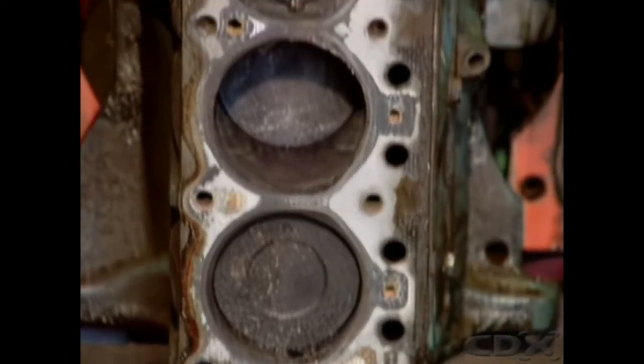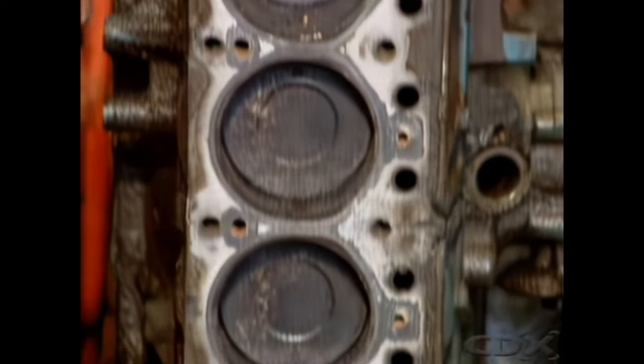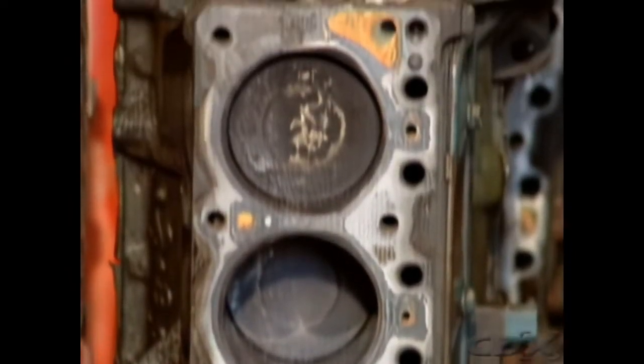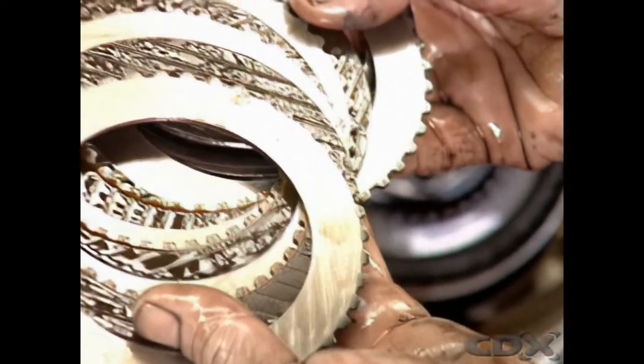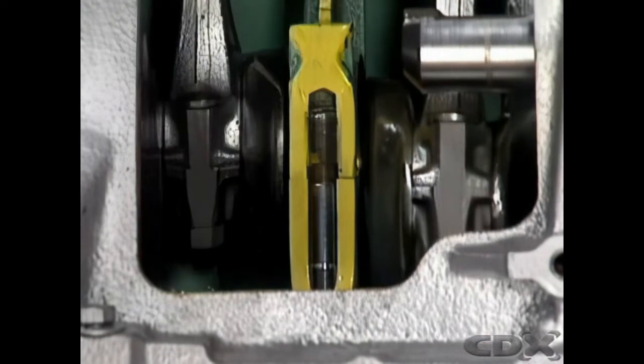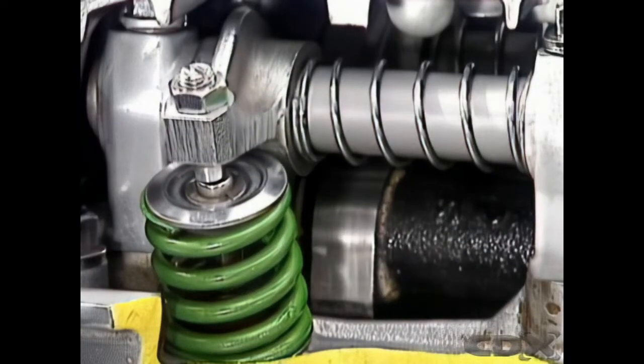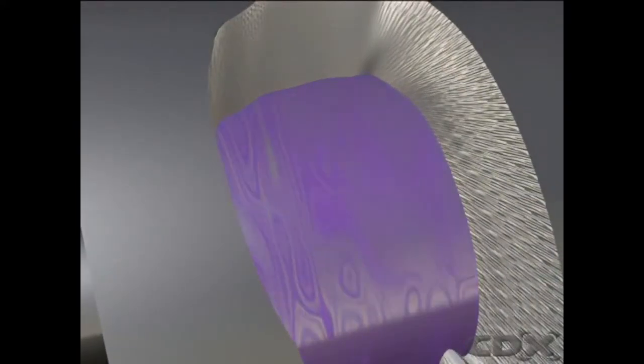How long an engine lasts depends to a large extent on how well it's lubricated, especially at the points of extreme loading. So lubrication reduces unwanted friction and controls it where it is useful. It reduces wear on moving parts. Clearances fill with oil so that engine parts move or float on layers of oil instead of directly on each other. Much less power is needed to move them, and that's a plus.